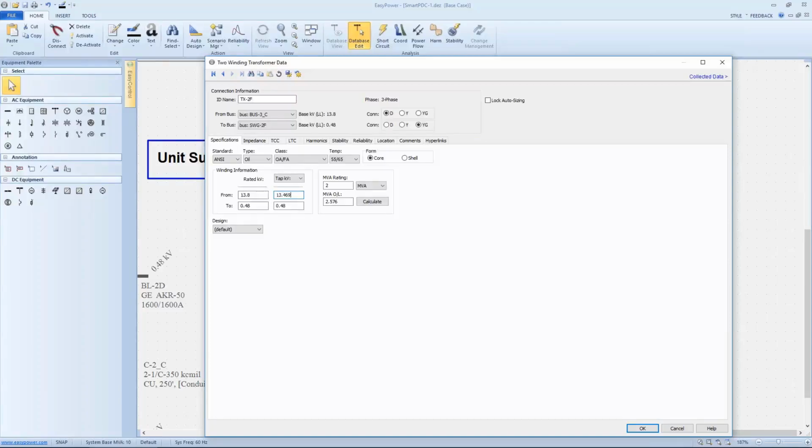The same thing is true if I have a spread from a utility company where it may be seasonally adjusted, and I don't want to put in an automatic load tap changer. I want to just find a common setting for taps that will keep the plant in the best case condition optimally over the seasons.